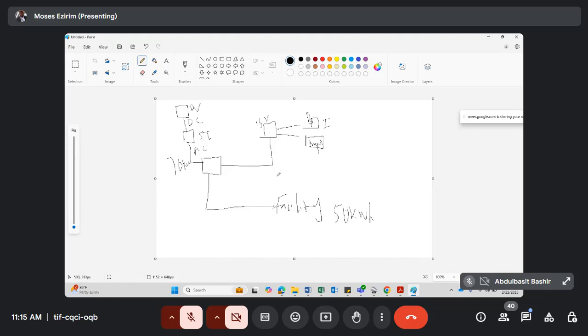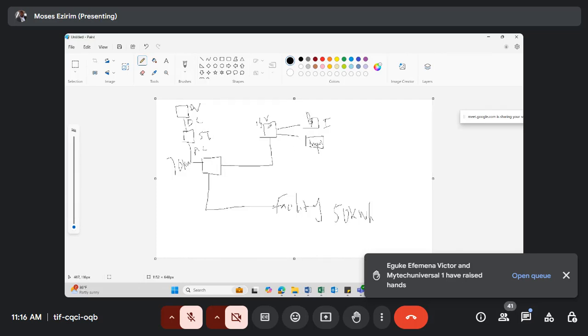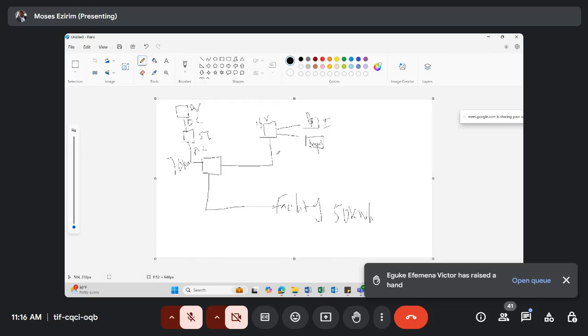So now once the load increases to 70, what will happen? It takes it again from the battery through this same output. Remember, the output is bidirectional. Through this output it powers all the loads. Do you understand? So now once it is night time and the energy from the PV is not working again, then through this bidirectional output, the battery will be powering the load. The input from our generator or grid can also be charging the battery and powering the system. So this is basically how your AC coupled system works.